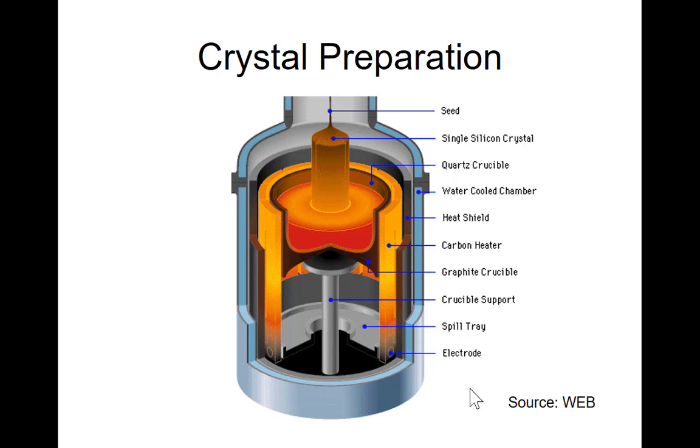From the top you lower a silicon stick, pointy on the bottom. You lower it until you get near the surface of the molten silicon. Then the silicon will begin to come to the rod, which is cold, and it will crystallize on it. As it begins to crystallize at the tip, you allow it to crystallize, and then it's going bigger and bigger. There's the tip part there.